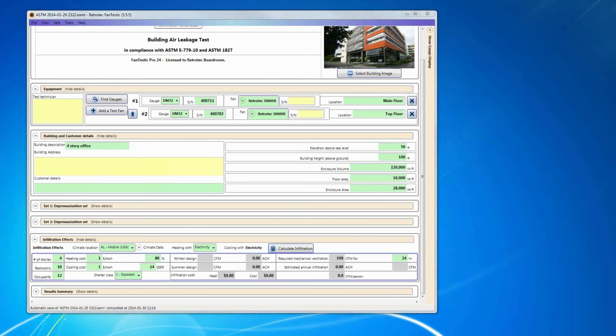I'm sorry I didn't run through a cost of infiltration analysis to make sure that my example made any sense. I did run through it several years ago when I put it together, and it worked fine at the time. The cost of infiltration analysis is really only good for a building of probably 5,000 square feet and down that looks and acts like a house, because that's the purpose for which that software was developed. It uses the infiltration model developed by Lawrence Berkeley Labs that was meant for residential houses.